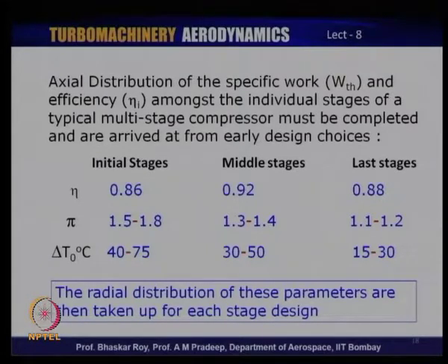The pressure ratio of the initial stages, in spite of low efficiency, is likely to be high, because you are operating at a low pressure and low temperature, and due to the low temperature operation, even with moderate amount of work input, you can get a very high pressure ratio. So, by design, most designers like to accomplish very high pressure ratio in the early stages, because in the later stages you progressively get less and less pressure ratio, to the extent that in the last stages you get very low pressure ratios anyway. So, by design, the designers like to put more work.